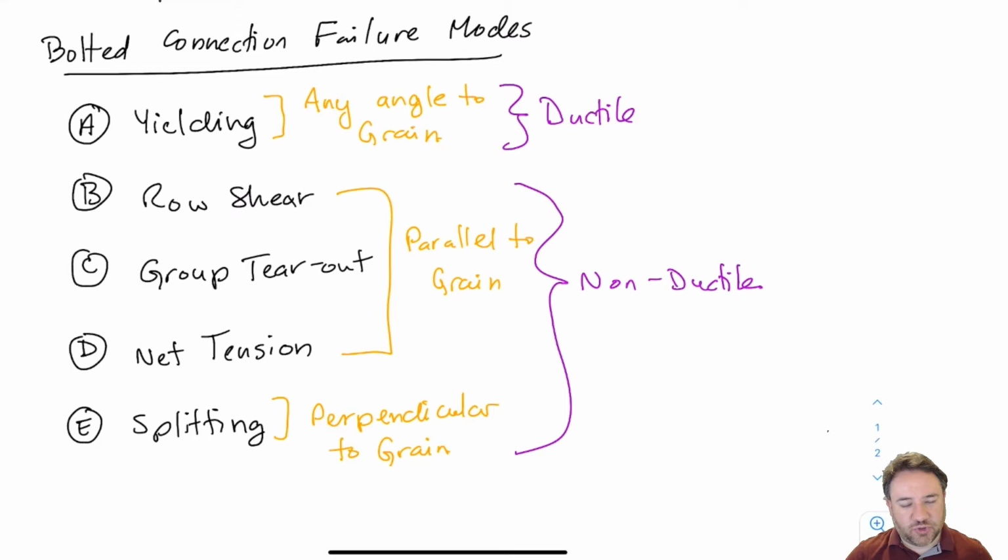So these are similar in style to what you see in steel design, but a little bit different because the strength of wood is obviously a bit different because the mechanics of wood are different. Reason being because wood is an orthotropic material, so we have weak planes due to the lignin joints that are holding the fibers together.